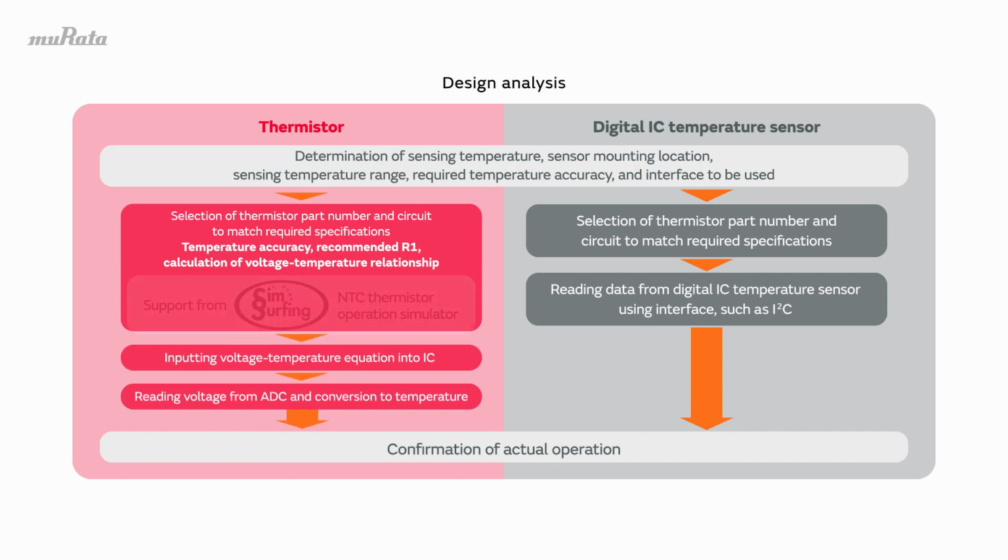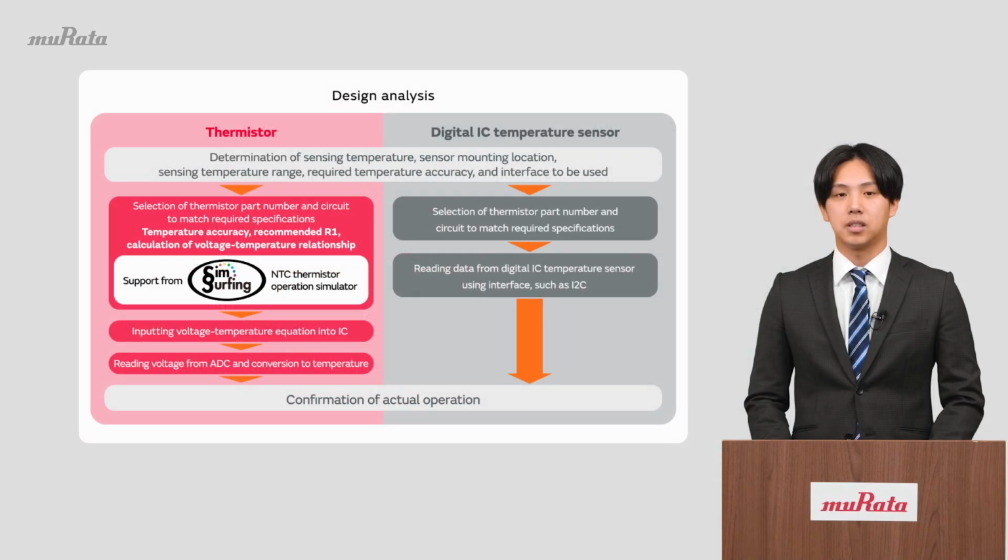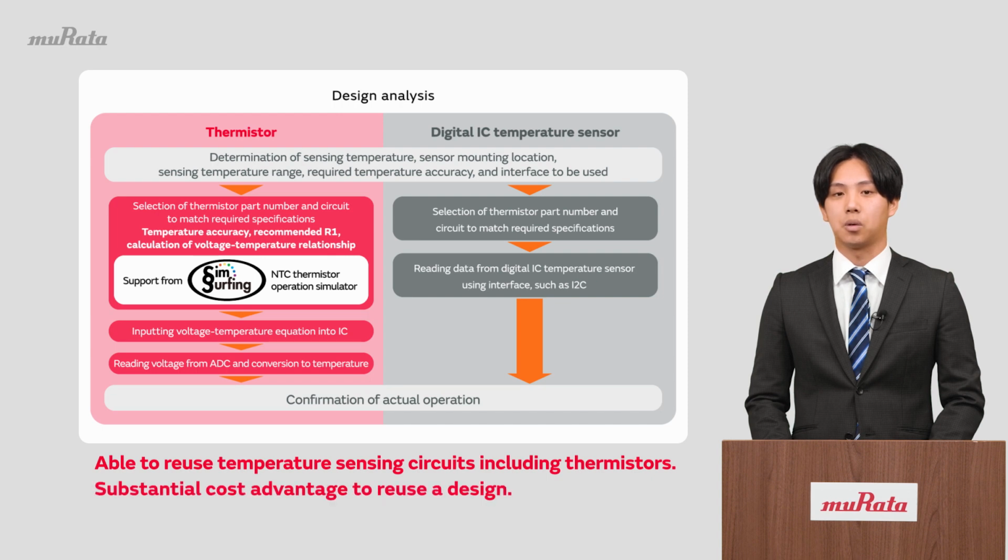However, if you use the SimSurfing operation simulator on Murata Manufacturing's website, making these calculations is a simple task. What's more, once you design a temperature sensor circuit using a thermistor, you can continue to use the same design moving forward. Continuous reuse of thermistor circuit designs can provide a significant cost advantage.